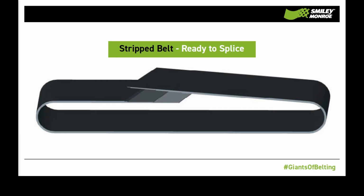Our ready to splice strip belts are a measured length of conveyor belt with overlapping stripped ends, ready for hot or cold splicing in your factory or on site. These belts are used most commonly when a belt is being replaced and the exact endless length of the conveyor is known, as it means we can pre-prepare the ends in our factory for the vulcanizer, therefore saving time and money.